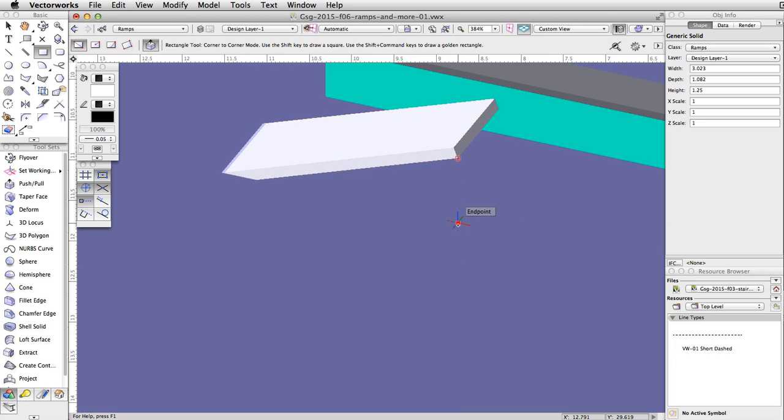Acquire a second smart point on the bottom right corner of the elevated face. Move the cursor down along the extension line until you intersect the concrete base. When the smart cursor cue Object/Y/Align Y appears, tab into the floating data bar and set the delta x to -0.15. Make sure the delta y is 1.25 and press enter or return twice to place the rectangle.